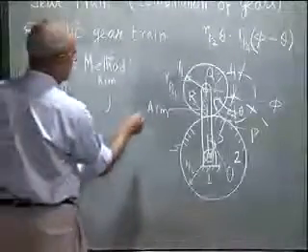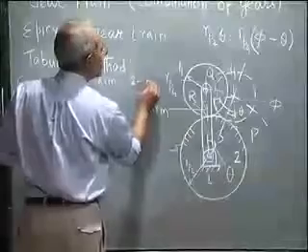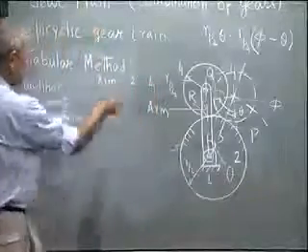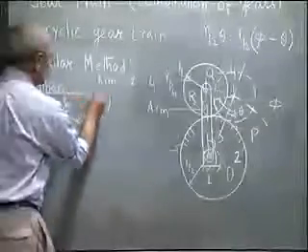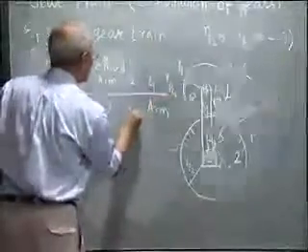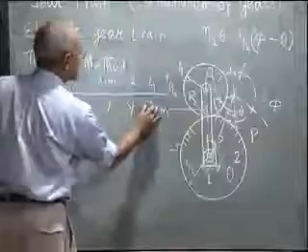Then all the gears, gears 2 and 4, because they are locked to the arm, under this condition, if I give the arm y revolutions, I will get y revolutions to all the gears.